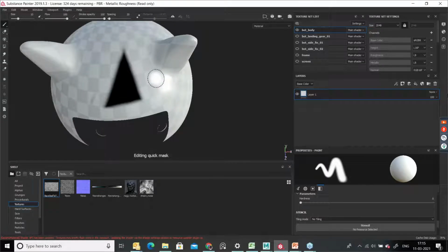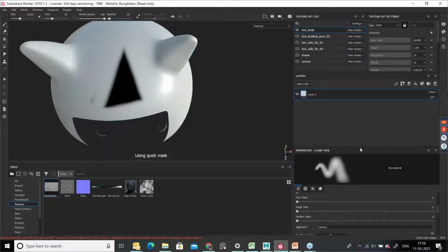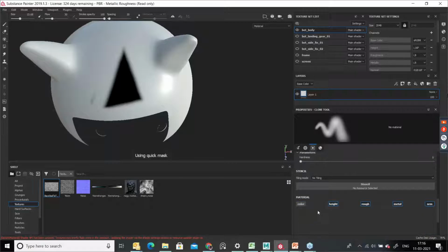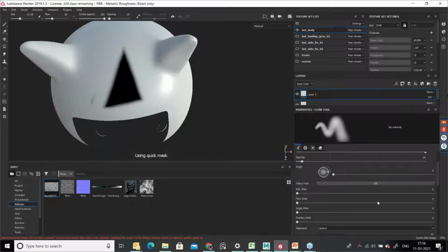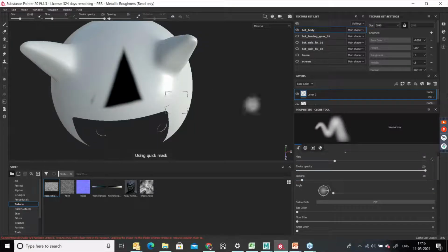Yes, we can press this. So how to do that? Yes, you can press U. U is the shortcut key to apply texturing in other area. You can change the color of this. You can just apply your texture information. So you can change the color, or you can add one new layer and apply color over there. So you can just go here. I think you can choose the color. It's not loading. So like this, you can apply one masking, and apart from that, you can apply the texturing process.